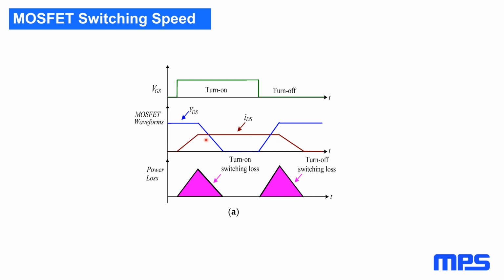Okay. How to select a MOSFET package? So it largely depends on PC board design. For most people, smaller is better. To use a surface mount package with limited heat sinking, you need to consider the RDS on and how much heat you can pull out of the device into the PC board. If it's a very high current, you either need very low RDS on, or in some cases, you might use a through-hole package with a heat sink. But it's really all about power dissipation and how and where you want to dissipate the heat.